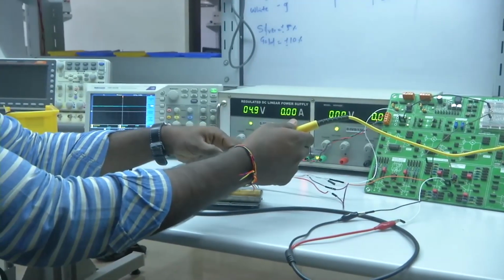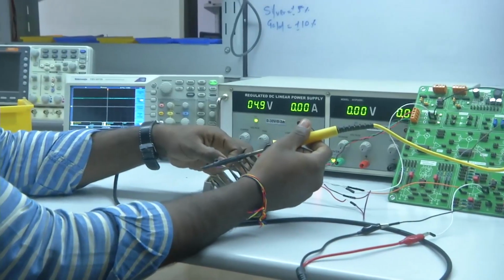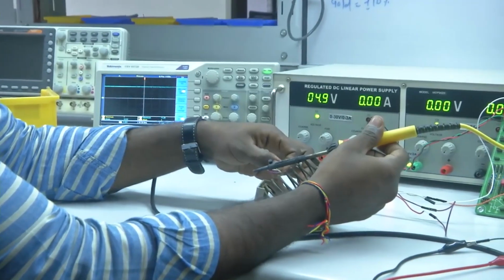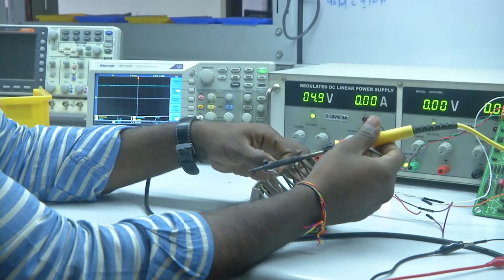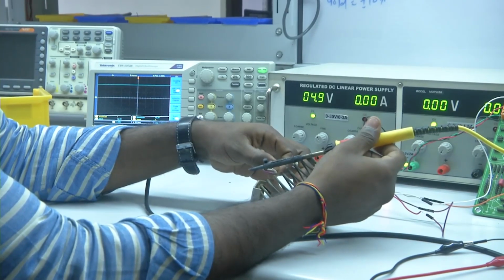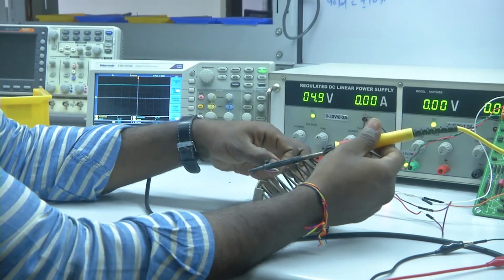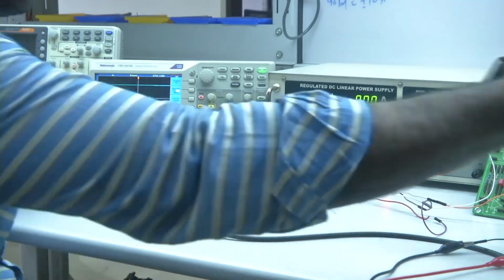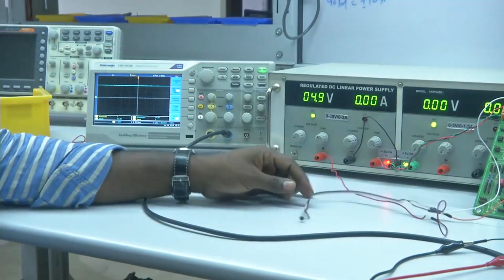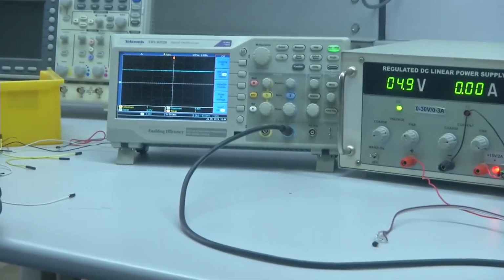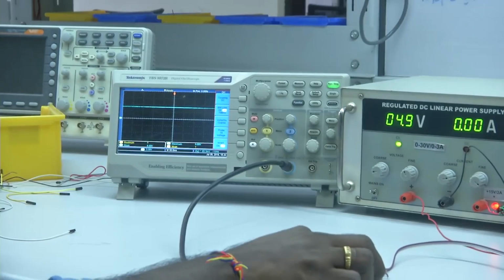Can you see it, right? You see, it started heating. Gradually it has come to 10.9, 11.2, 11.4, right, 11.8. So, now the heating station has heated to a little high temperature. The maximum voltage it is showing is 12 volts, which means that, if we consider the gain of 10, it is at 120 degrees centigrade. Now I have removed the connection, and it will slowly come down because of convective cooling, to room temperature.